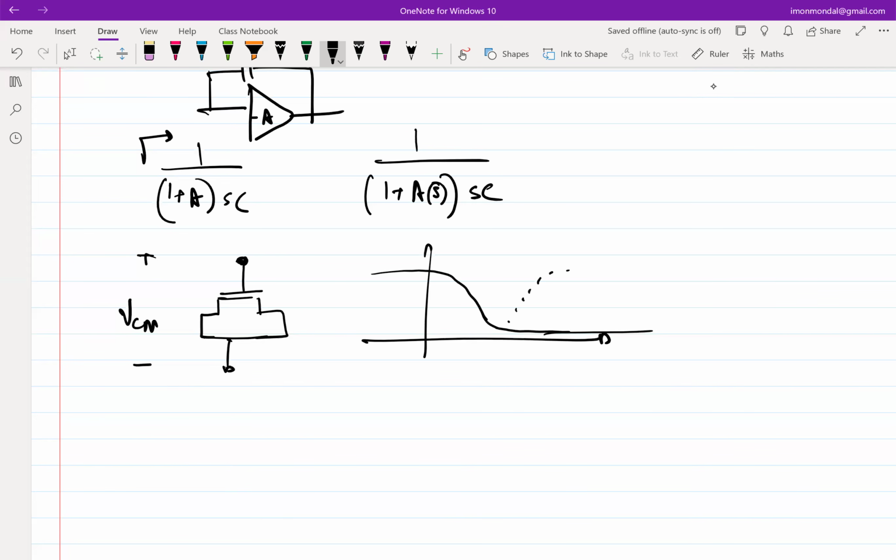This is low frequency stuff, but we are talking about high frequency, so we don't have to bother with whatever is happening at low frequency. So here we have the accumulation phase. Here, I should say C effective, and this is VCM. When VCM is 0, that is accumulation mode, you have Cox times WL by WL. And here you get C depletion, right?